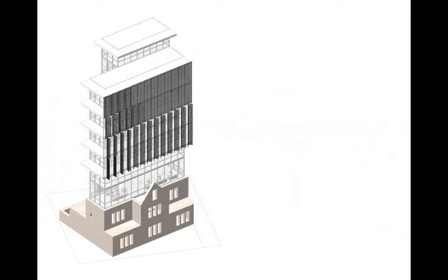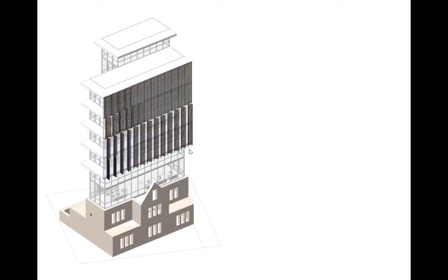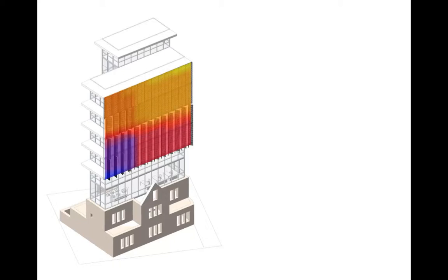And that's the view of the building. And I think I overlay in a moment. Yeah, look at the shading, the degree of closed shading, open shading. And then we overlay the solar radiation onto it. I'll just go back. And you can see that shading, it's not approximate: the north facade has less shading, the south facade has more shading. It's a really optimized relationship with the solar performance.